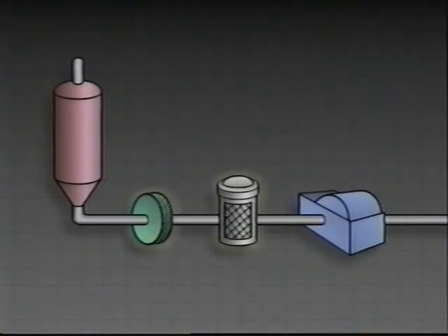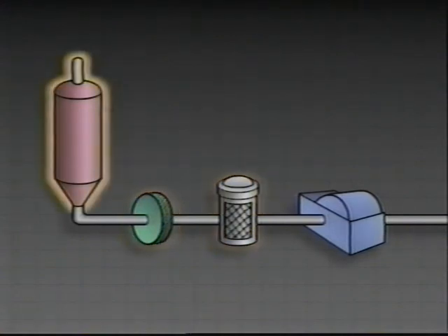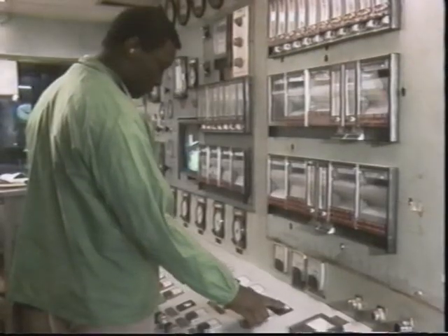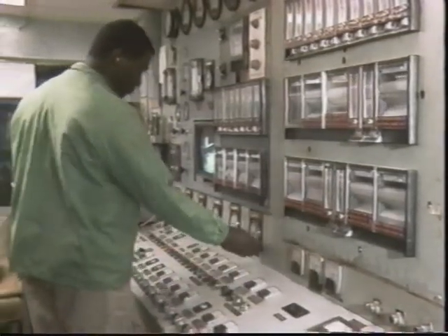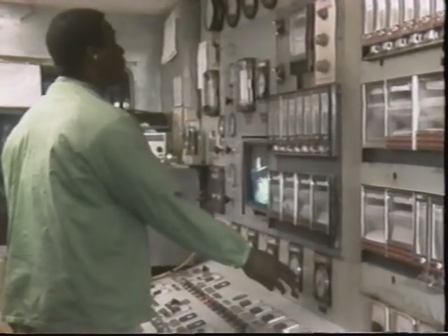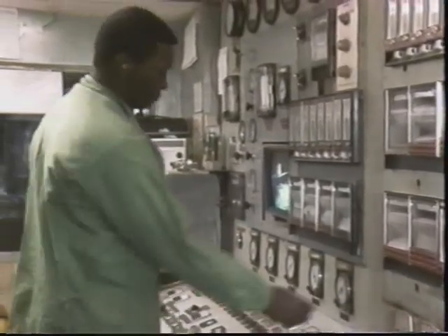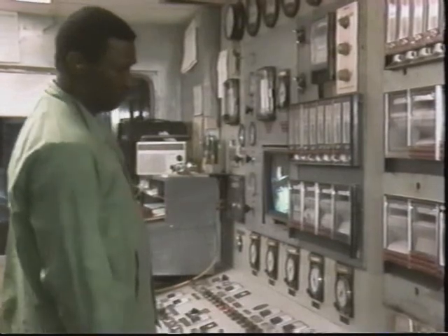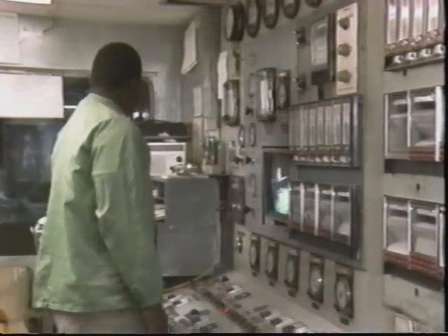In this example, inspecting the screens and refiners would require that the equipment be shut down and taken apart. But you can get a good idea of operating conditions in the digester by simply referring to the process variables in the control room. So the operators will check the digester before they try the screens and refiners. Also, the digester can be checked out without reducing production rates or shutting down the process completely.